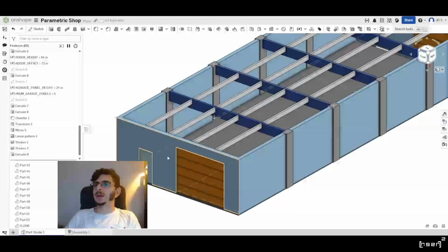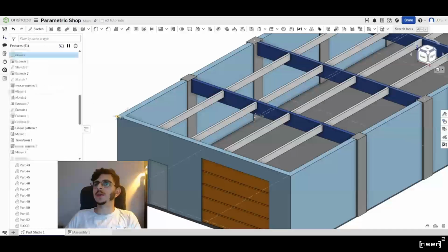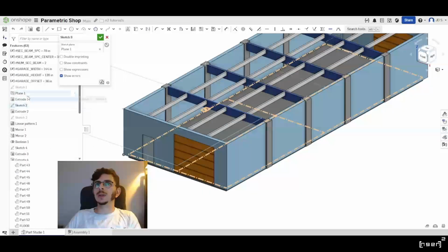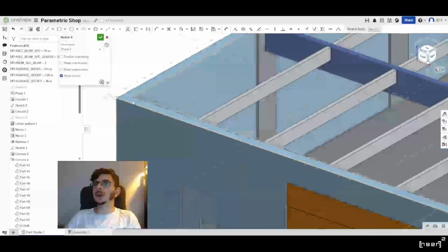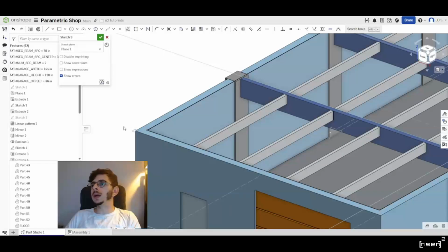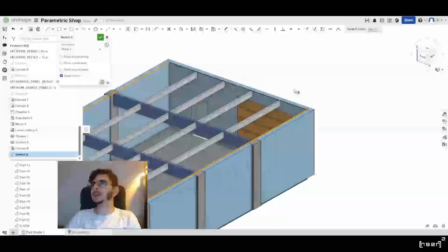And we will, yeah, let's make another one. We'll make this one pretty thin. So we'll go sketch and then we will straight up project sketch one up to here, and we can make this a construction line.